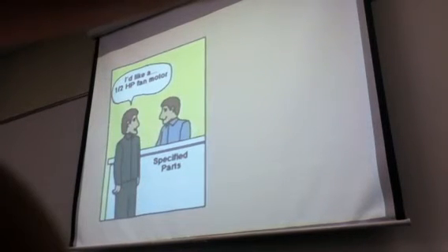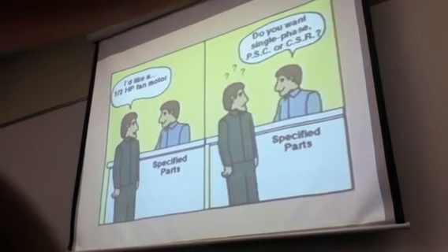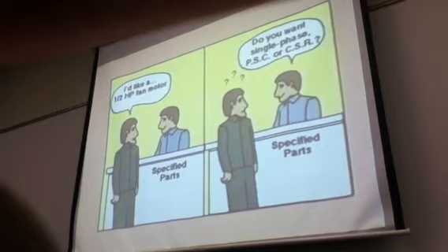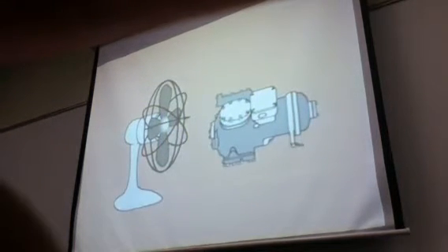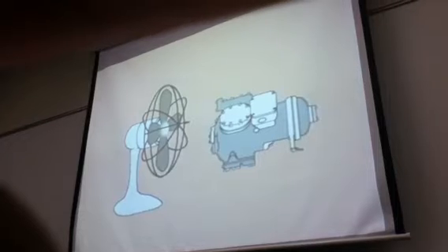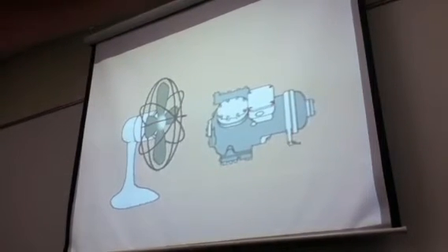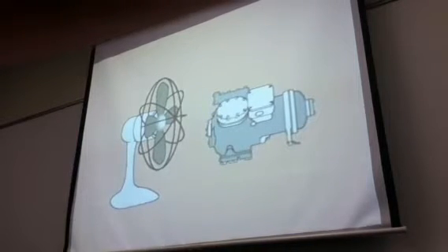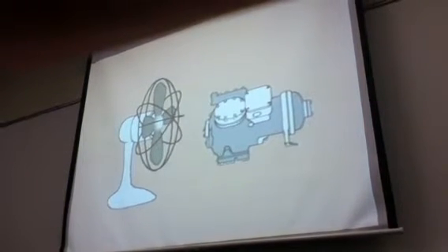Air conditioning and refrigeration systems use many different kinds of AC motors. It's important to be able to recognize and troubleshoot the various types. Why are there so many different kinds of electric motors? The answer is that different motors do different jobs. The selection of a motor is based on the amount of torque it must deliver and the speed at which it must run. When these two criteria are satisfied, power consumption is considered.